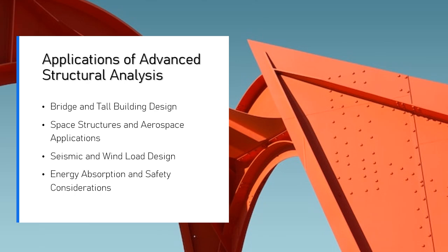Advanced analysis: computational tools like SAP 2000 or ANSYS were used to perform dynamic analysis of the bridge. These tools help simulate seismic load scenarios and assess how the bridge's structure will respond to earthquake forces. Nonlinear time history analysis and response spectrum analysis were employed to model ground motion and simulate the bridge's dynamic response.